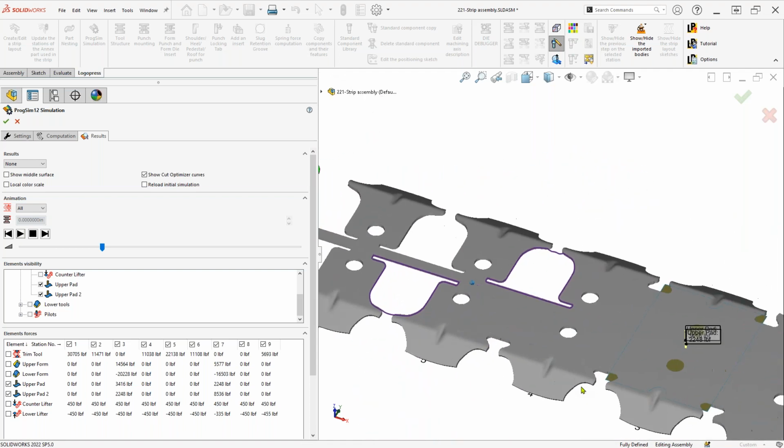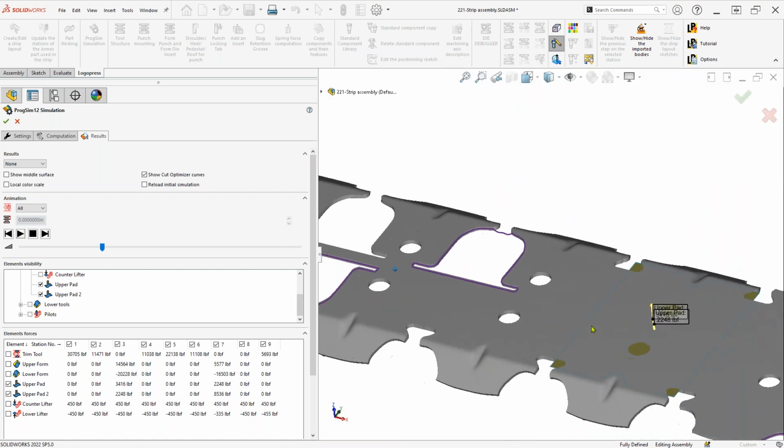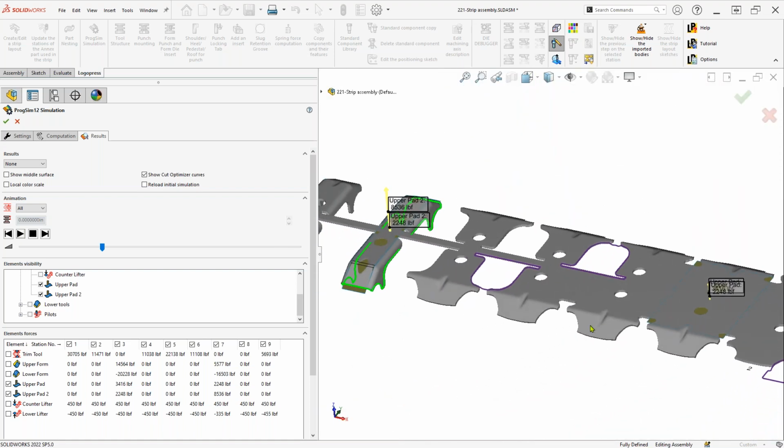And that's not to say that it wouldn't potentially work with something less, but especially when you get into thinner panels, when wrinkling is going to occur. But on something like this, if you had less, it wouldn't stay perfectly flat. It would start bowing the part up, that top portion of the part. When AutoForm sees that the part starts to move, it keeps pushing down until it doesn't move anymore. Is that a correct way of saying it, Paul? Yep, that's correct. Okay. Yeah.